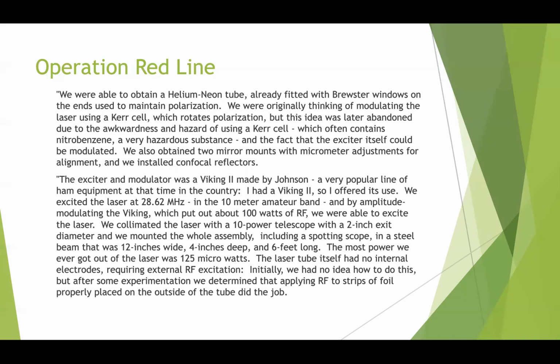The laser tube itself had no internal electrodes, requiring external RF excitation. Initially, we had no idea how to do this, but after some experimentation, we determined that applying RF to strips of foil properly placed on the outside of the tube did the job.